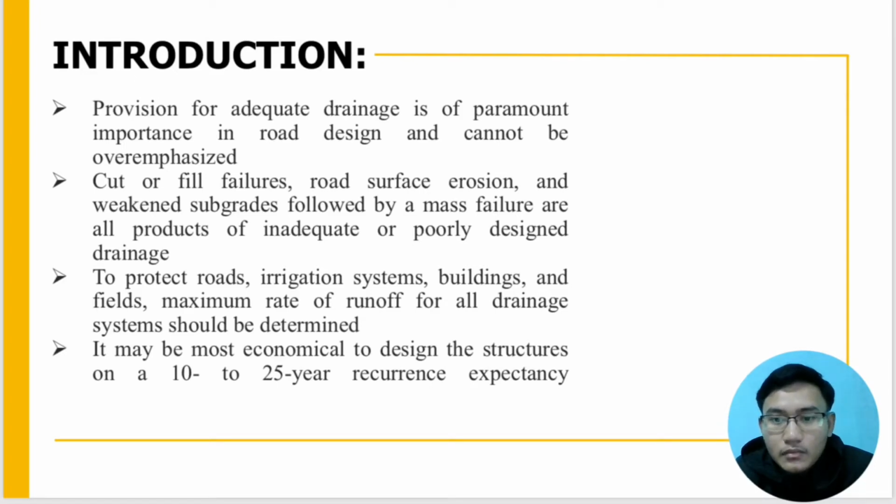Fourth, it may be most economical to design the structures on a 10 to 25-year recurrence expectancy. That is, the expected runoff will be exceeded only once every 10 to 25 years.